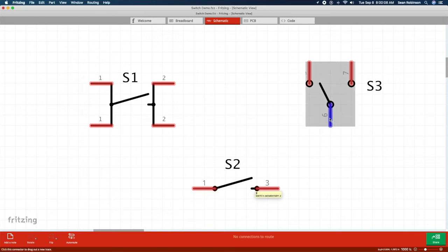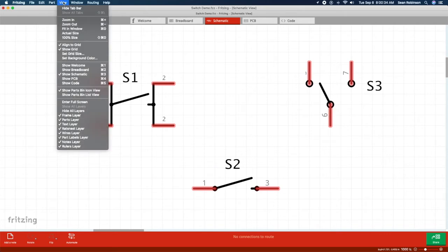With this one here, when you flip the switch one way, the electricity goes from here over to this pin. When you flip it the other way, it goes from here over this way to this pin. So that's where the single pole double throw comes into place. Now there are some that are called a double pole double throw, which means that there's two of these. And let me see if I can pull one of those up real quick.